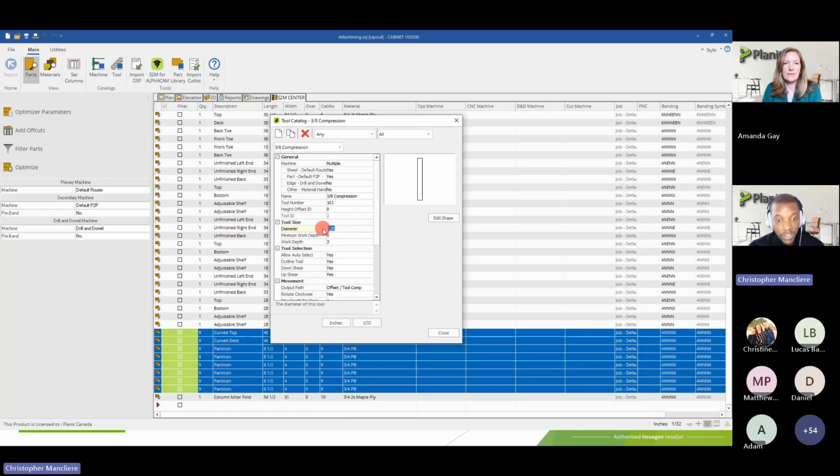So CAD will say my tool is spec'd as 3/8. The operator says, okay, it's 3/8, but it's a little bit less, so you will adjust it on the machine. And when you use tool compensation, when the program is being run, the machine will look at the real diameter of the tool and compensate the position, moving it slightly to get the right position for you.